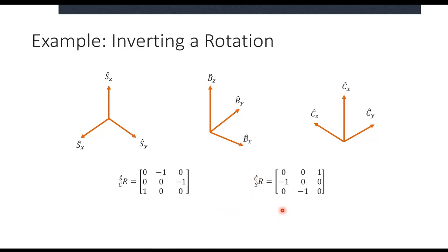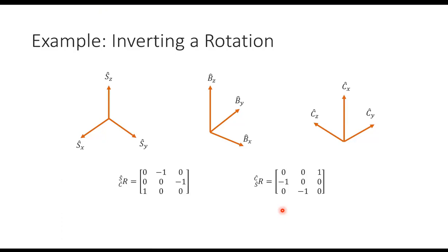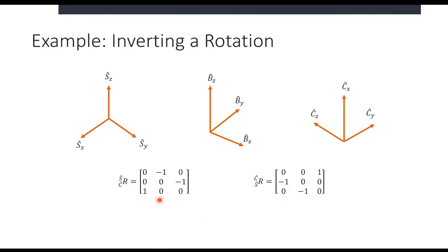And most of you probably saw this on the homework 0 warm-up: when asking for the inverse of that matrix question, we gave you some words in the question that suggested that these are rotation matrices. It turns out that to invert a rotation, you only need to take its transpose. So you can see that these matrices are the same thing, just transposed.